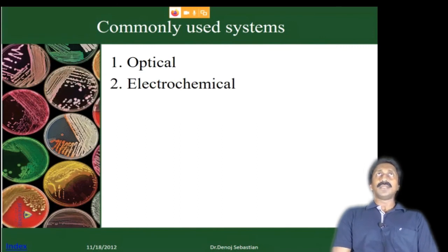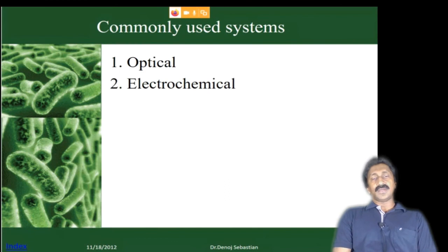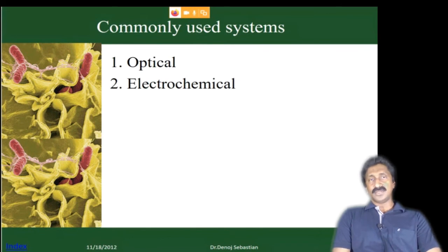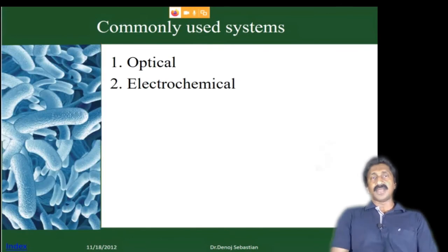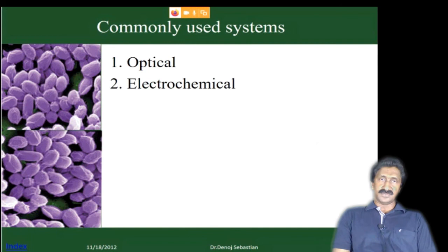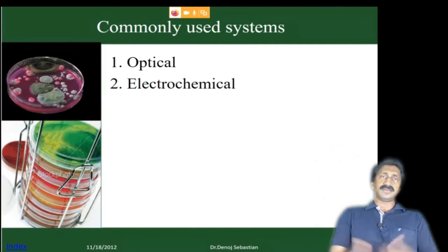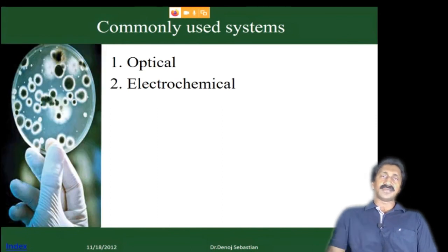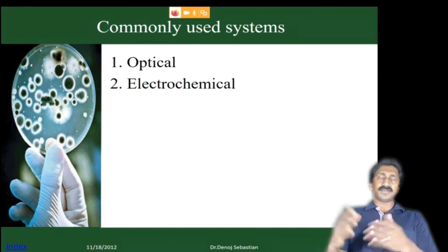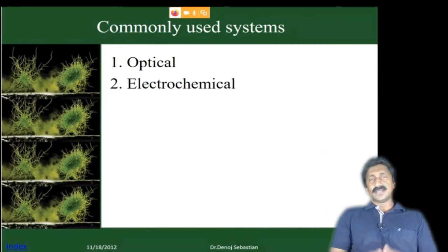And one advantage of this SPR technology is that you don't have to add any markers for detection. Usually, such biological detection methods may require some binding of markers or some probes for identification. But here, that is not required, because only target receptor interaction on the surface of that SPR plate will result in the electrical deflection, and subsequently that deflection in the optical path will result in the identification of the analyte and the concentration of the analyte.